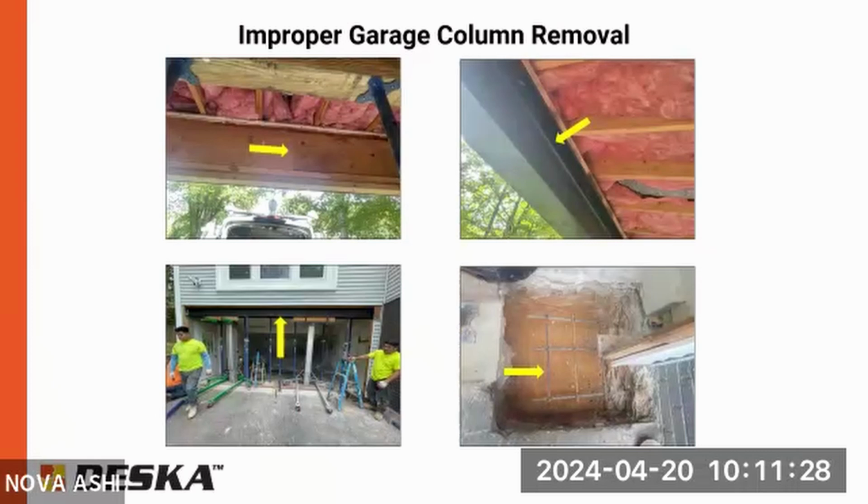So half the roof goes to the back wall, half the roof goes to the front wall usually. And if, let's say, the house is 30 feet deep, you have roughly 15 feet, half that roof load, coming to this front wall.